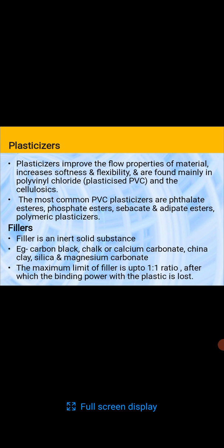Plasticizers improve the flow properties of material and increase softness and flexibility, and are found mainly in polyvinyl chloride, PVC, and cellulosics. The most common PVC plasticizers are phthalate esters, phosphate esters, sebacate, adipate esters and polymeric plasticizers.